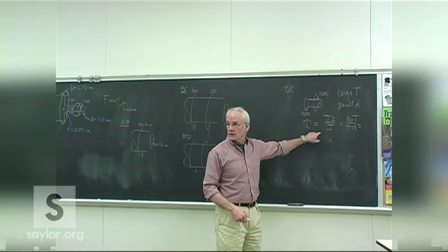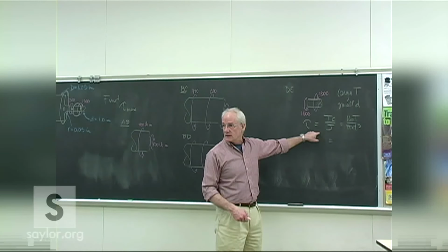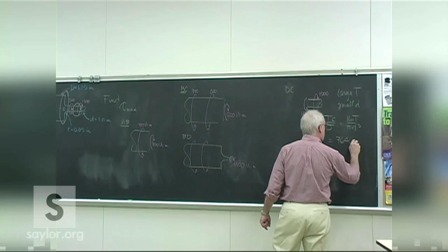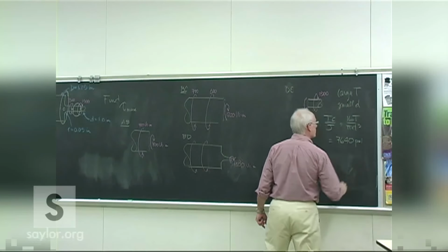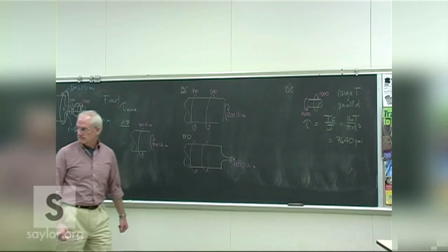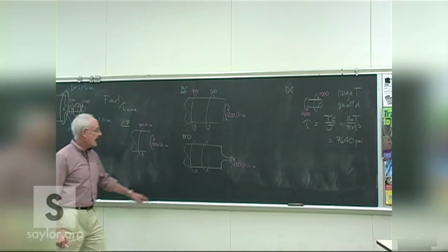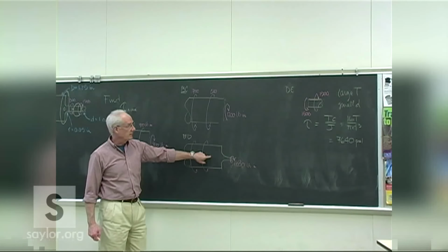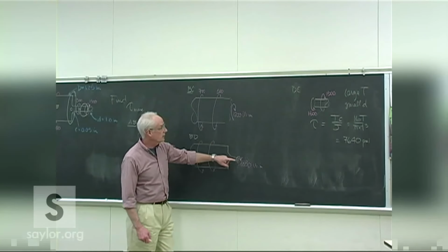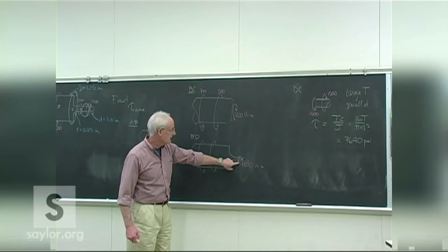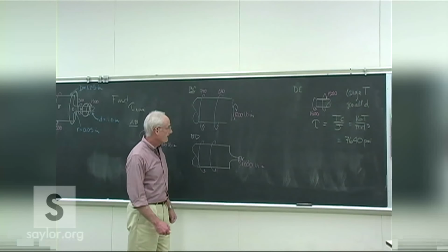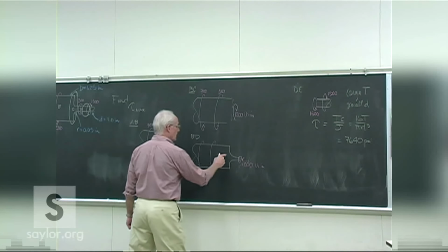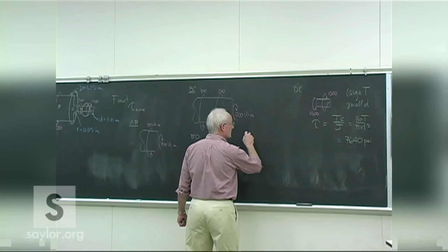Does anybody have this one? 7640 psi? Yep. Now, that's actually the lower number on this one, because we'd have 1200 in here instead, because we're at the slightly lower load, but we have the stress concentration factor.